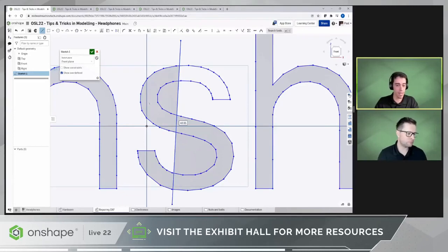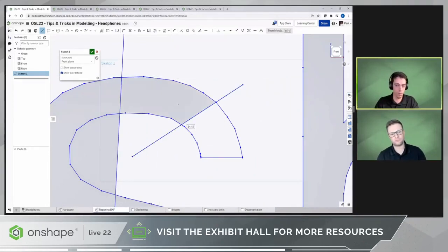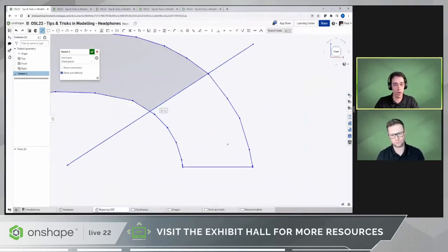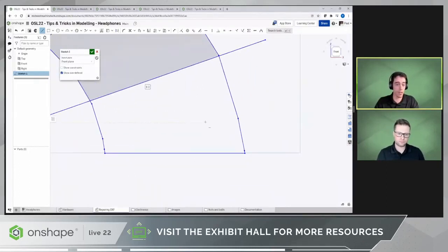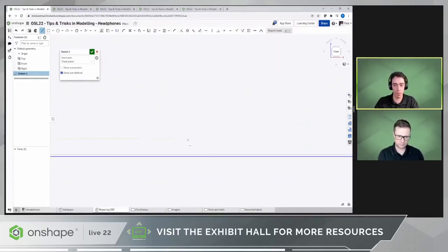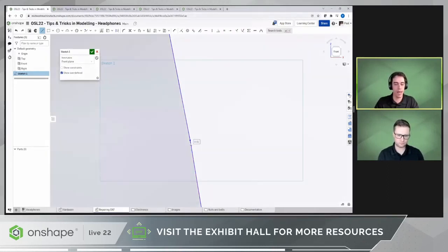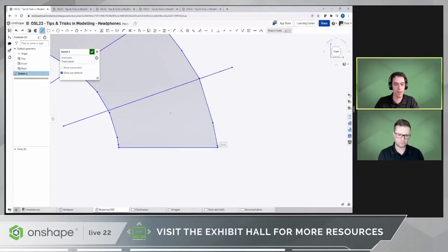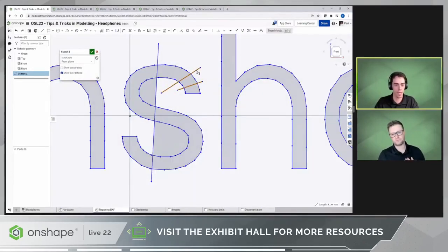As you can see here, this area is now closed. Let's add another one over there. And it's closing too, of course. I could add another one here. Right. And so it has to be now one of these points here, right? So let's check those points one by one. And there it is. Here is the little gap, right? So I can just close this. I can delete the lines, and that's done, right? My problem is solved. I repaired my DXF, okay?